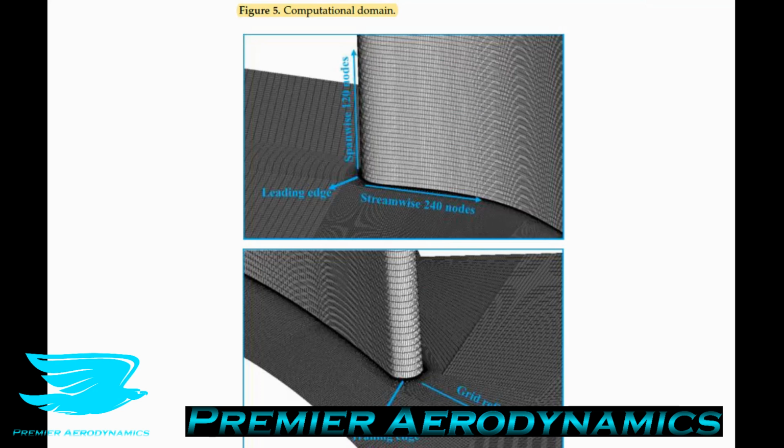So this is a fairly low turbulence intensity level transition path, and it's fairly hard to predict. Bypass transition is far easier. This is where you have a very big disturbance and it just transitions instantly to turbulence there. So that's much easier to model.